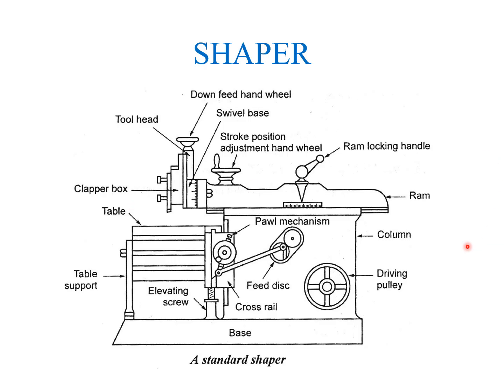Then column. The column is attached to the base. It provides the housing for the crank slider mechanism. The slideways are attached to the upper section of the column which provide the path for ram motion. Then crossways. It consists of vertical and horizontal table slideways which allow the motion of the table. It is attached with some cross movement mechanism.